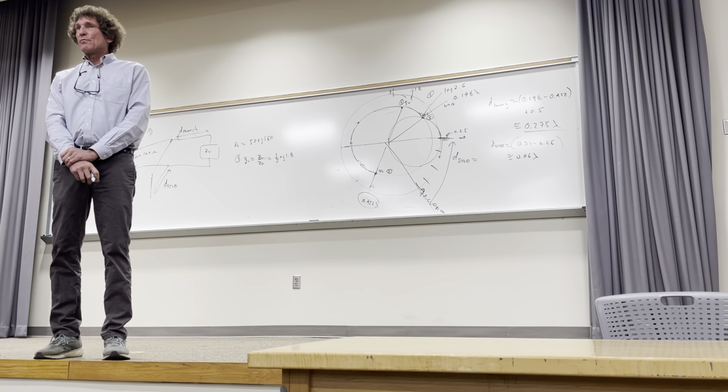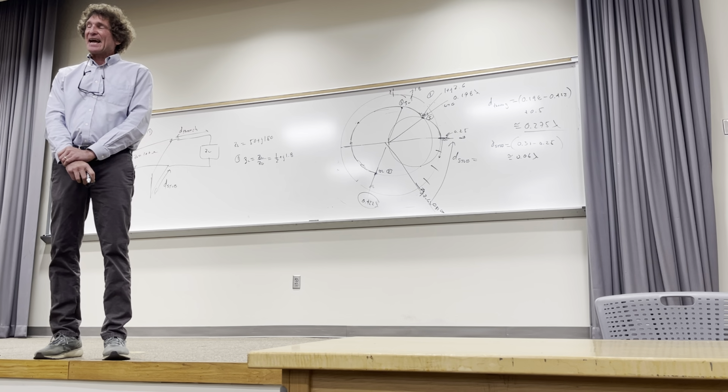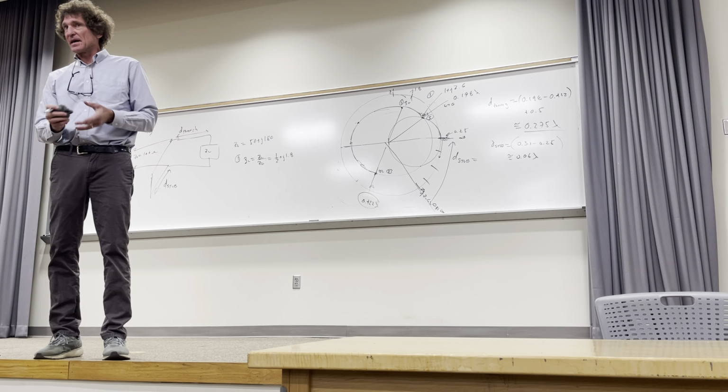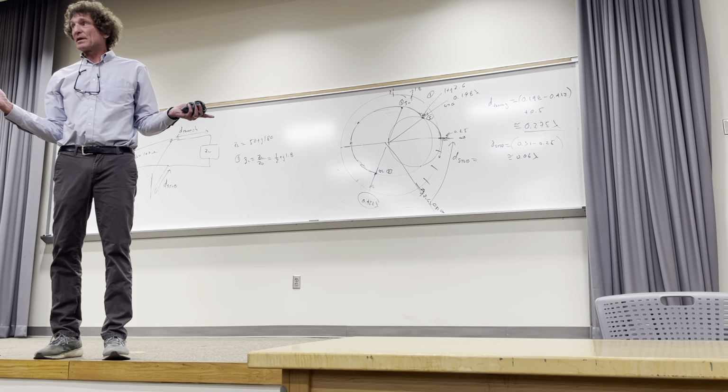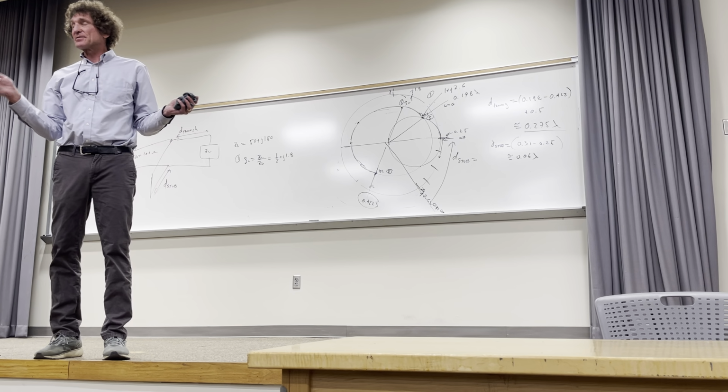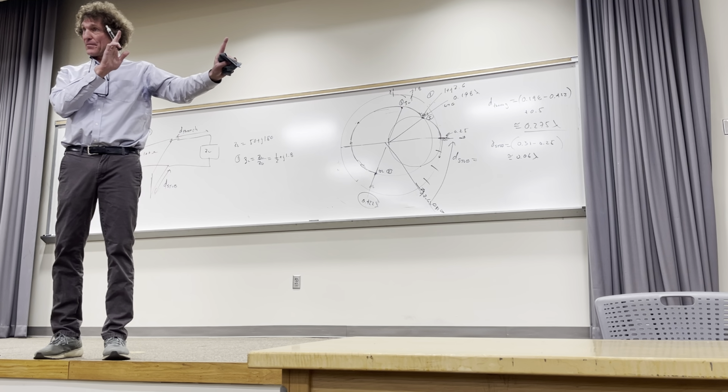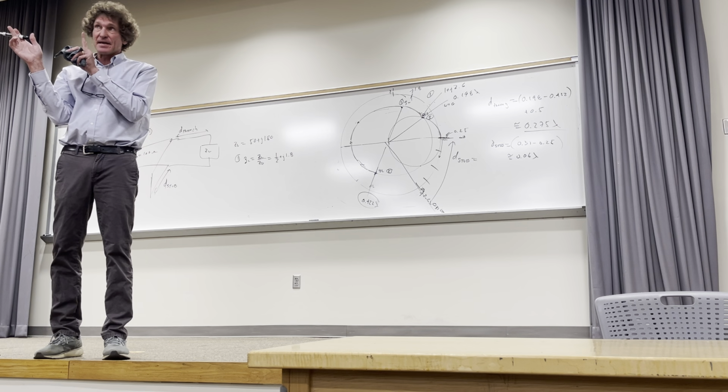How long does any kind of transmission line have to be in order for it to behave as a transmission line and not two pieces of wire? This is an inexact science, but a tenth of a wavelength? Is that a tenth? No. So really, we're under that, but believe it or not, because there's not a hard, perfect behavior, it's a transmission line if it's over a tenth, and anything less than a tenth isn't.